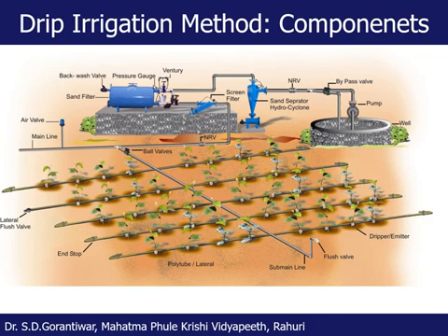Now when do we have to use the media filter? Normally when we use water from an open well or reservoir or pond, there is possibility of debris, because these could be covered by trees and so on nearby. So there will be debris and leaves, and as they are exposed to sunlight, there are chances that algae develop there. So whenever we have water from these sources, and whenever there is a possibility of such organic matter in the source, then we have to use the sand filter.